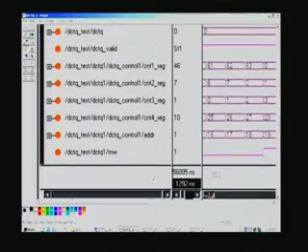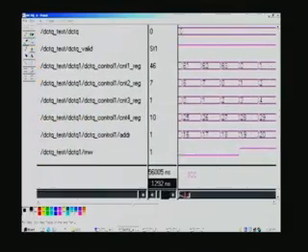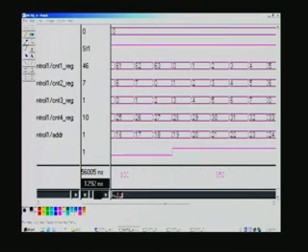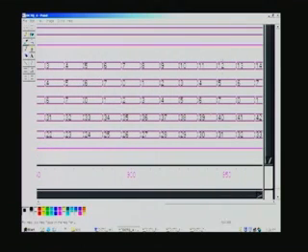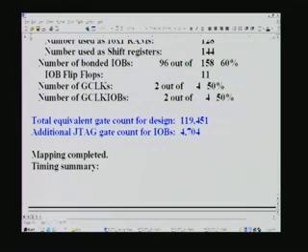So, we will go straight away there. Now you can see it has completed the very first block data writing. Counter 1 is for the DA input for the dual RAM here, and it has completed here. Because it has completed, R and W is once again automatically switching. So, not a single clock cycle is wasted. It is a continuous firing of input image, so also the output, and output also you can see here, and this is not yet complete, we will see in the next waveform.